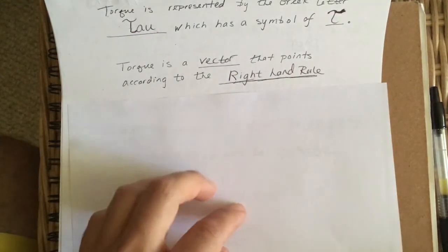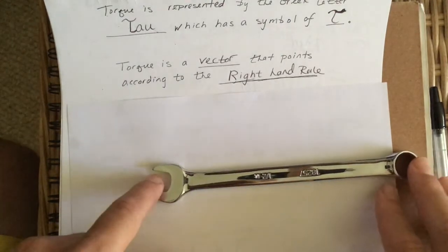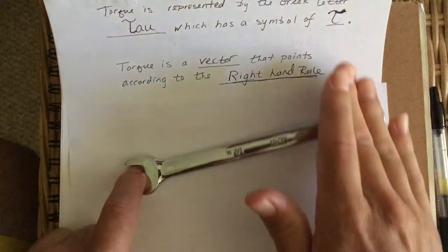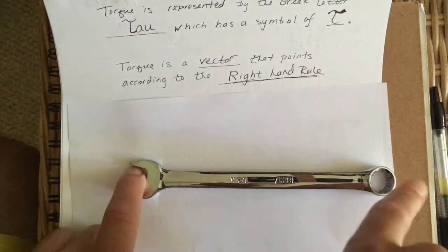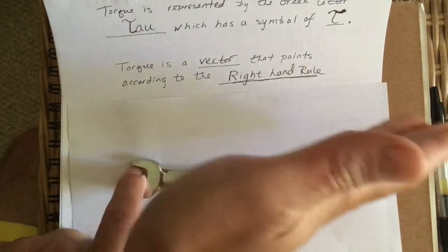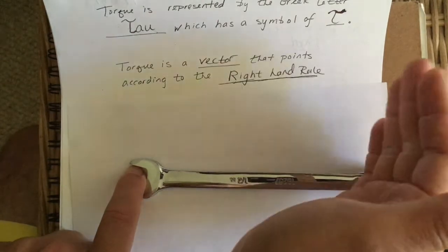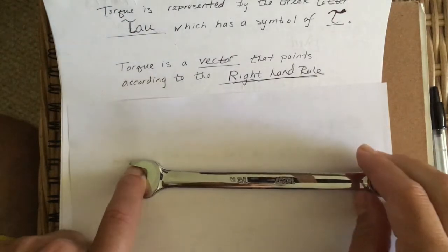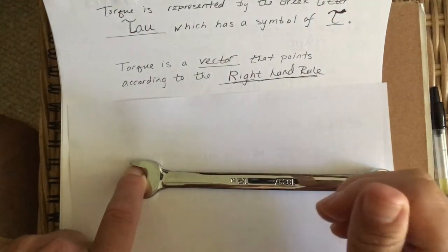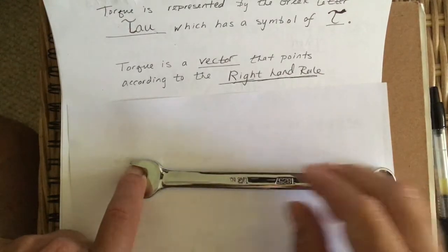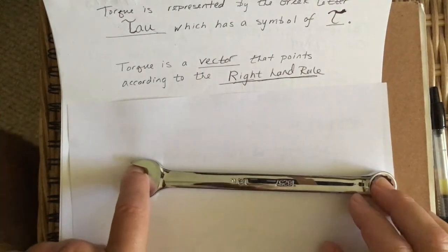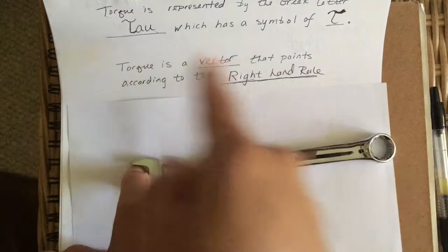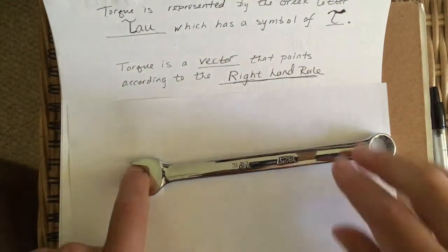So the right-hand rule works like this. Once again, if the pivot or the nut is right here and you're turning about it, you use a force, right? You push up, say, and the distance is this way. The right-hand rule says you point your hand in the direction of R, you curl in the direction of force, and the way your thumb points, which is towards the camera or up, is the direction that the torque points, out of the page. But before we do that, we're just going to refer to a force in this direction as counterclockwise, and we'll refer to that as a positive torque.